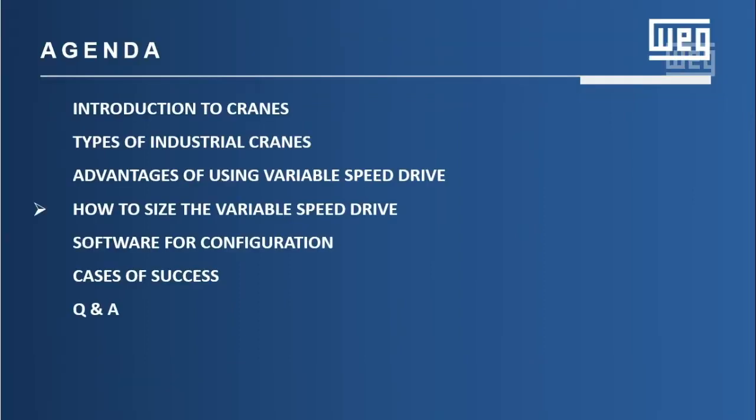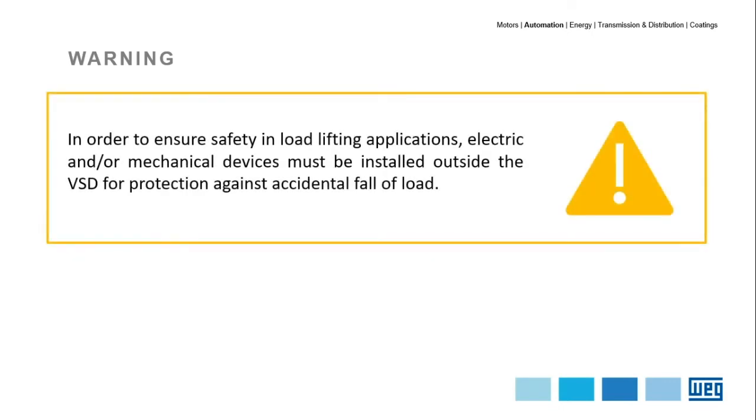So now we are going to enter into some suggestions by WEG on how to size the variable speed drive. Before we enter into this step, I would like to give you some indications that in order to ensure safety in load lift application, electric and mechanical devices must be installed outside the VSD for protection against accidental fall of load.